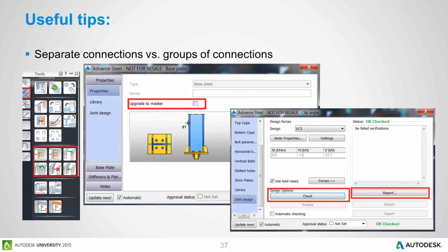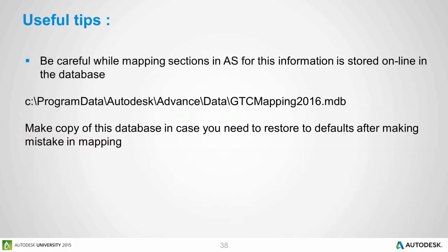And just mind that the selection of profiles you decided on during mapping is stored in the database and automatically used by Advanced Steel for all selected projects. It is recommended to make a copy of the default database in case you need to restore the defaults.